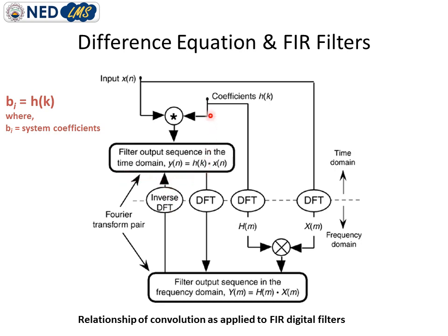Now the other side of the picture is this. Suppose we are not convolving the two inputs, but we are first taking the transform pair of these two inputs, which are the input sequence and the impulse response. If we take the FFT of the input signal, you can see that here we are taking the DFT of our input signal, then our input signal is converted into the frequency domain representation, and the same we are doing with the coefficients hk, which is the impulse response in time domain.